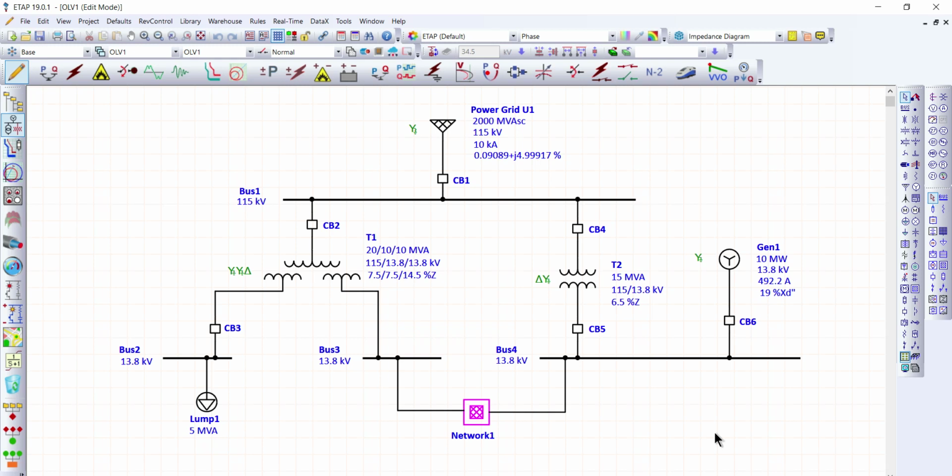The purpose of short circuit studies: to verify the protective device closing and latching capability, to verify the protective device interrupting capability, to shield equipment from large mechanical forces, thermal stress or I²T protection of equipment, and fault data obtained is used for relay coordination settings.